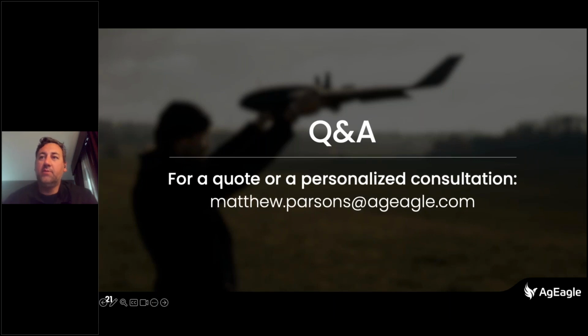So the GNSS question, Ildion asks, what happens if there's GNSS spoofing or jamming? There are user-defined safety settings, so you can define the time of the lack of response from the GNSS to the aircraft itself, or if there's jamming and the frequency cannot communicate. Once again, it's going to go into those return to home protocols that you've user-defined. When the GNSS is jammed, you have that terrain data already loaded on your ground control station. That's how the aircraft will return to home safely, because it already had that data in there. It's its first mechanism once it's lost GNSS for a specific period of time.